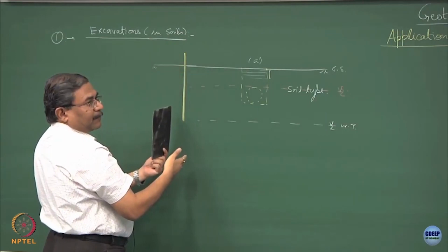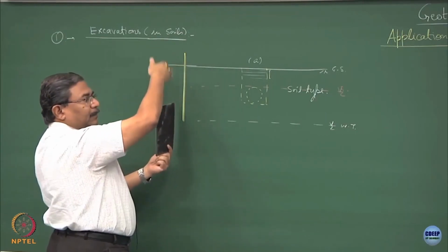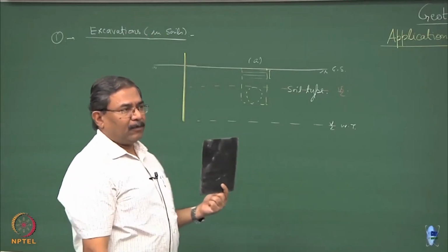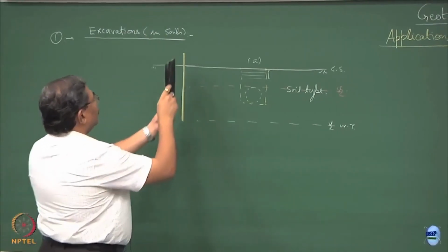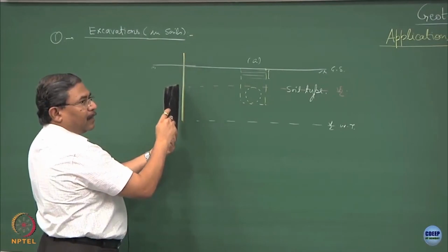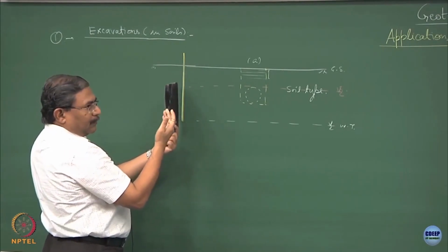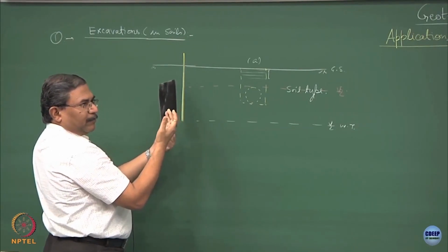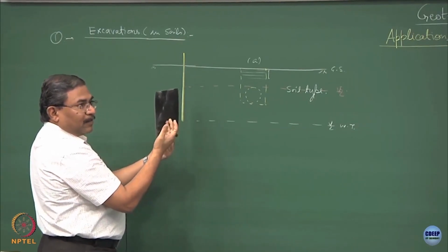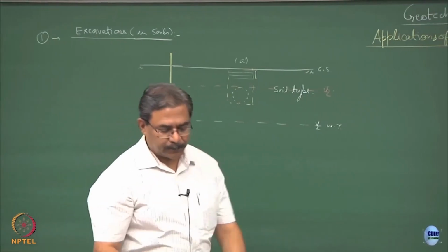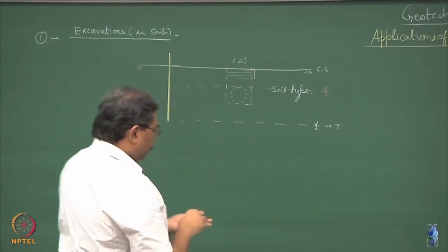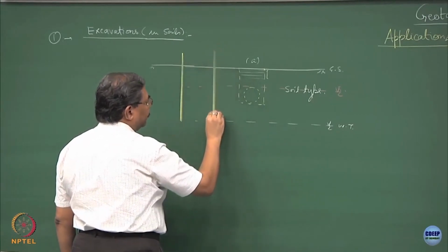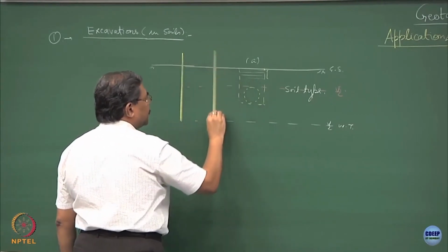Excessive depths can also be achieved by welding the 2-3 elements. Normally, these elements are 10 meter long, 5 meter long depending upon your requirement. So, this is what is inserted over here. This could be made up of steel, this could be made up of any composite, this could be made up of even concrete also depending upon your requirements, fine. So, another couple of this I will be inserting over here. So, this is a sheet pile system.